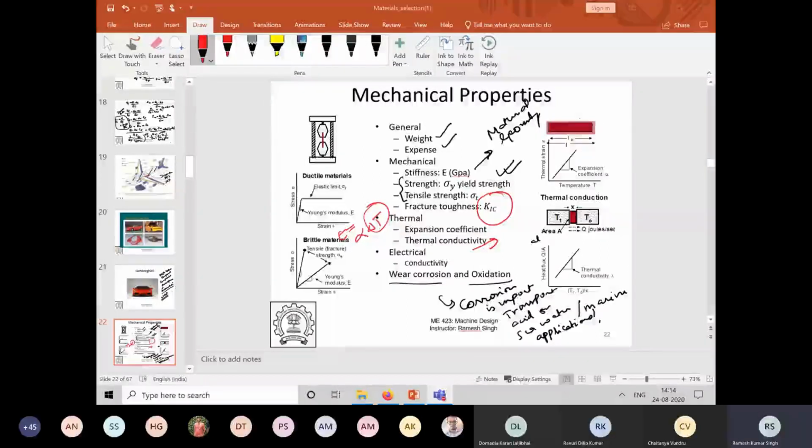Where do you think? So very correct. The low thermal conductivity basically means that, very good answer. All of you are saying low, because low thermal conductivity means the heat will be locked, right? The heat will not be diffused. The moment it is not diffused, you will get a localized temperature rise. So there will be a local temperature rise, and there will be lower temperature far off from there. So you'll have a high delta T.